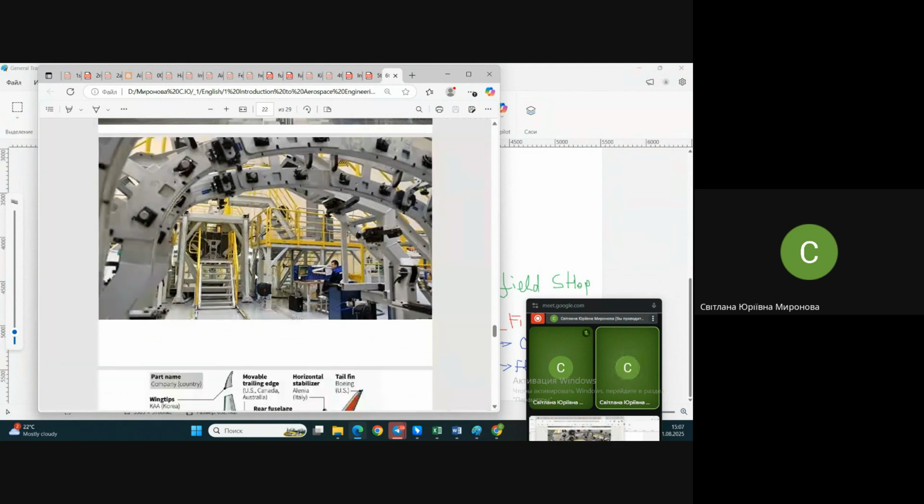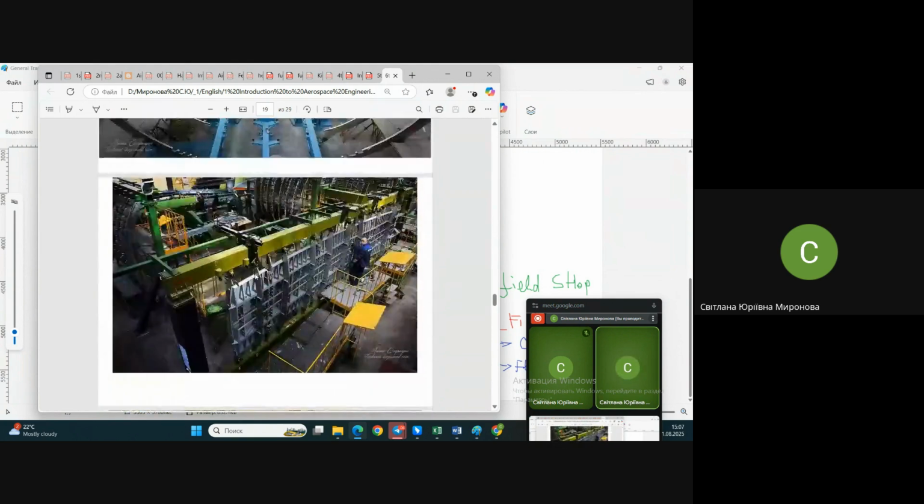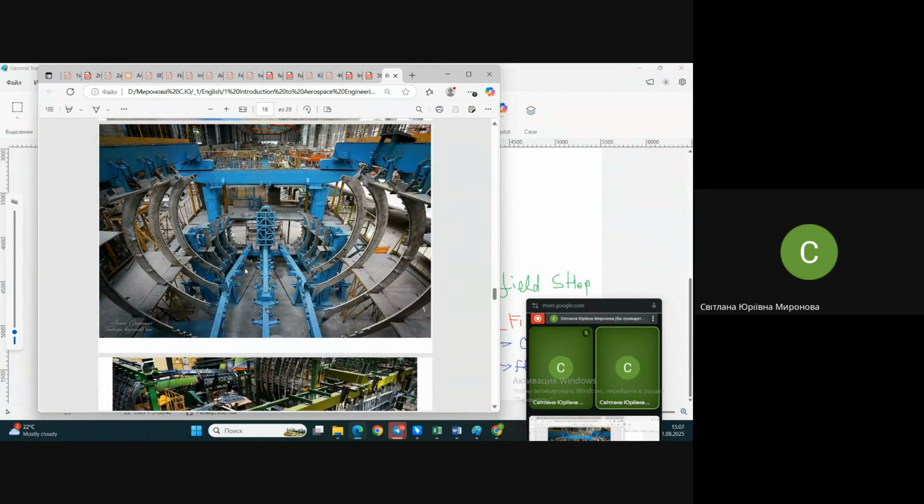Very well, but do pay attention to such an effect. For instance, to this one. Look, this thing that is a tool, seems like, for our assembling. It's not a tool, actually, it's a tooling, because, to be frank, it may be considered a tool. Those things which are so-called locators, the basis of the assembly jig, you place the elements of the structure onto these locators. And these locators are responsible for finding the proper place with respect to each other. In terms of transformation of spatial position, they will be the tool. Well, typically, it's called tooling.